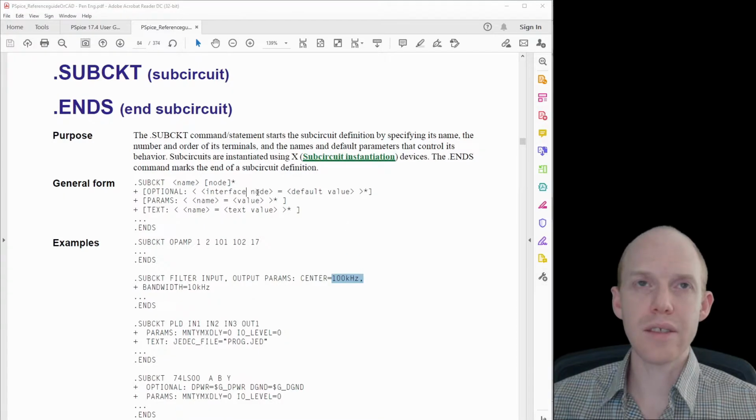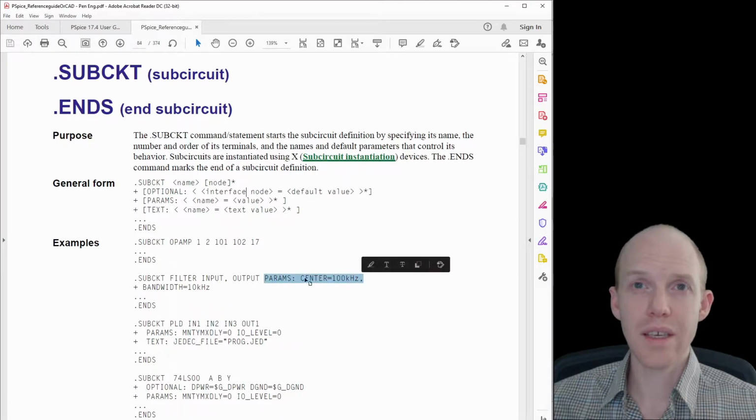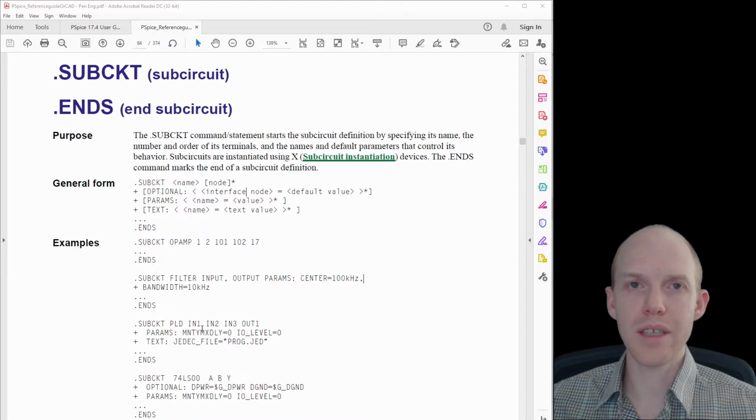And the other thing you can do with subcircuits is you can wrap elementary models in them. So the dot models, you can have a regular part with a dot model, and then you can parameterize that part by using this subcircuit with the params, and then these can be the parameters inside the model, like a BJT, for example. And in that way, you can instantiate different BJTs in your circuit using this wrapped subcircuit, and give them each their own parameters, if you just have one parameter that you want to be able to change easily, like the VBE or the beta or something like that.